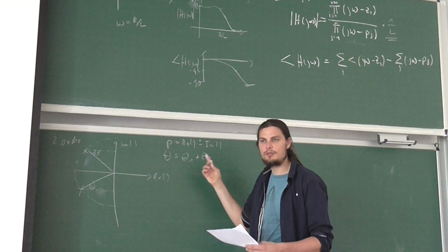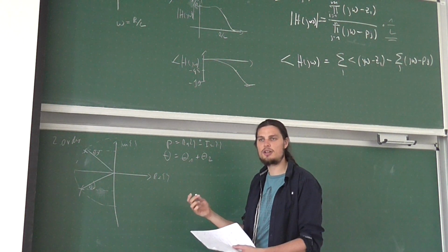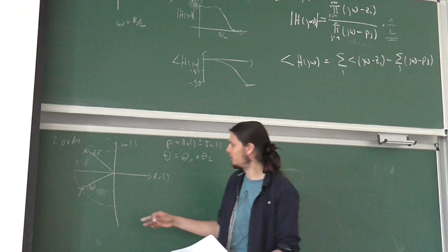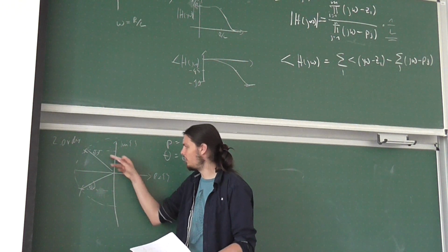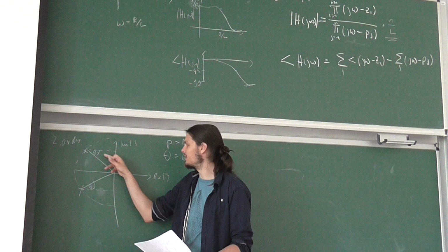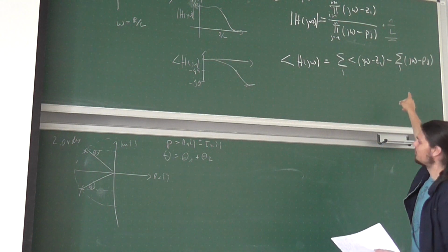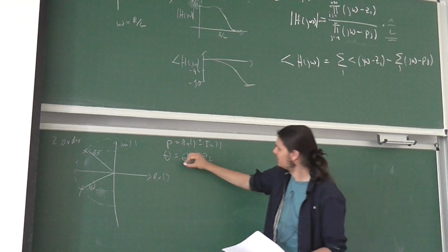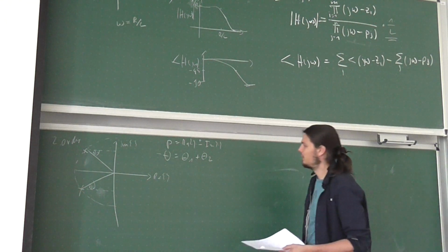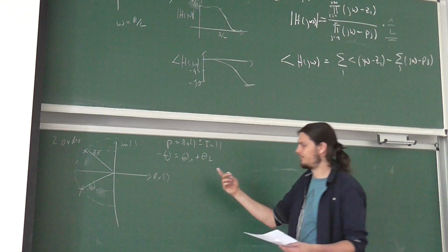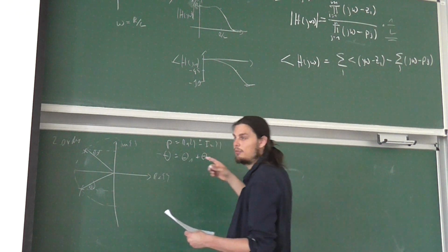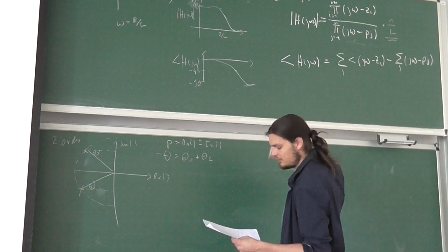So it very often happens if you have a second order system, you have a complex conjugate pair, right? And the overall angle you can basically calculate like this, as we said, right? So they add up, and basically minus of that. And also the magnitude would be multiplied onward, as we have already shown.